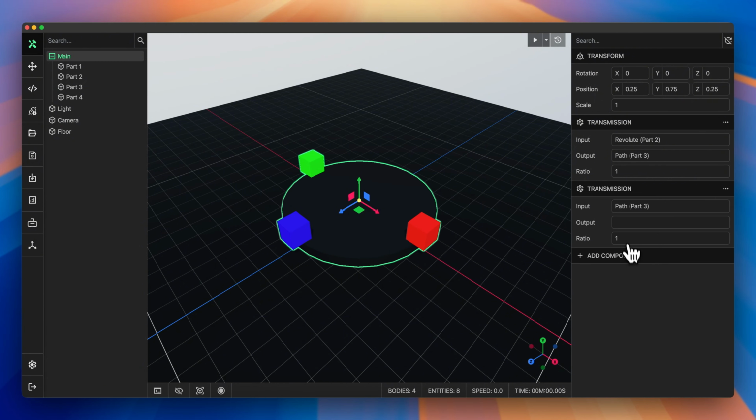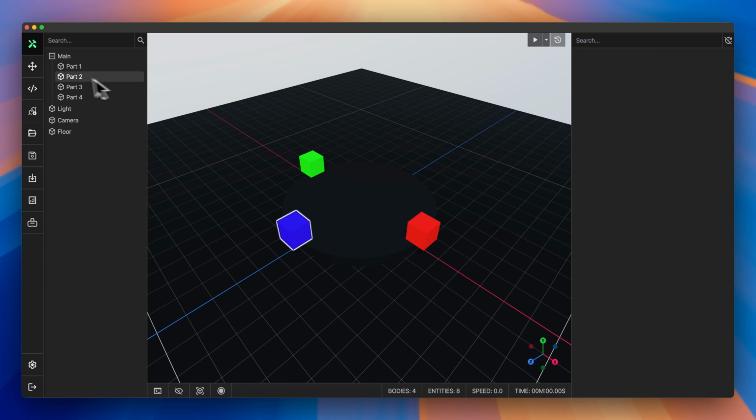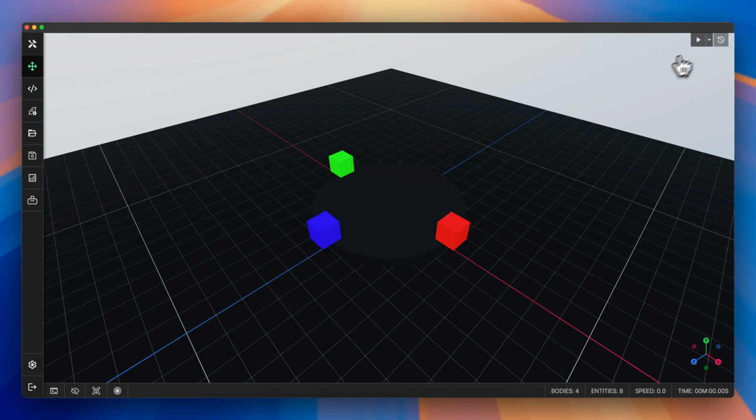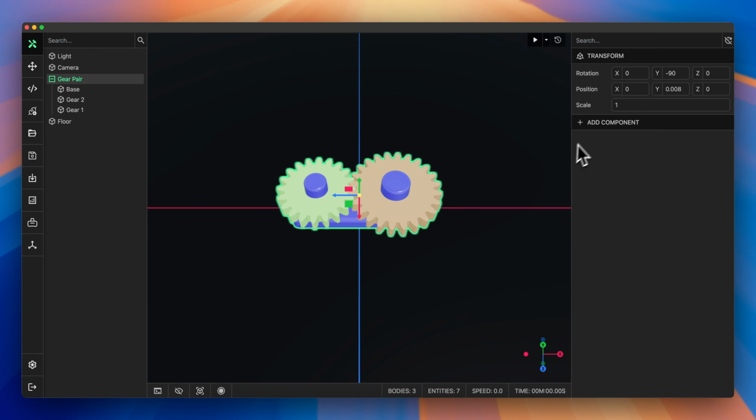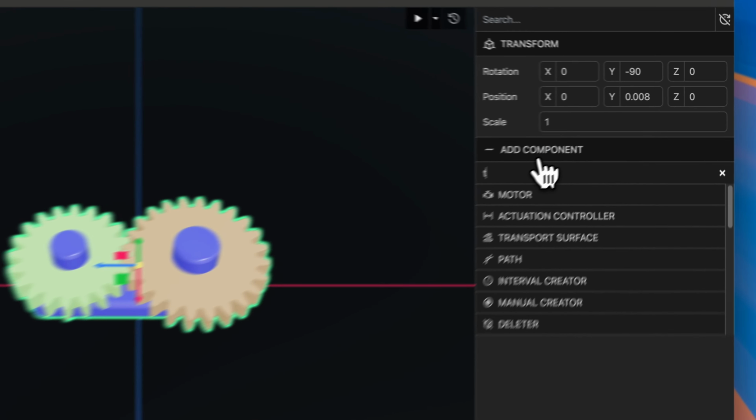The second transmission component will be used to relate the last two joints so that all the joints are constrained to have equal positions. If we run the simulation, we can interact with the physics to test our model. The constraint is solved entirely by our physics engine as part of the overall system of constraint equations. Unlike other physics simulators that constrain only the velocities, the transmission component ensures that the positions of the joints do not drift apart over time.